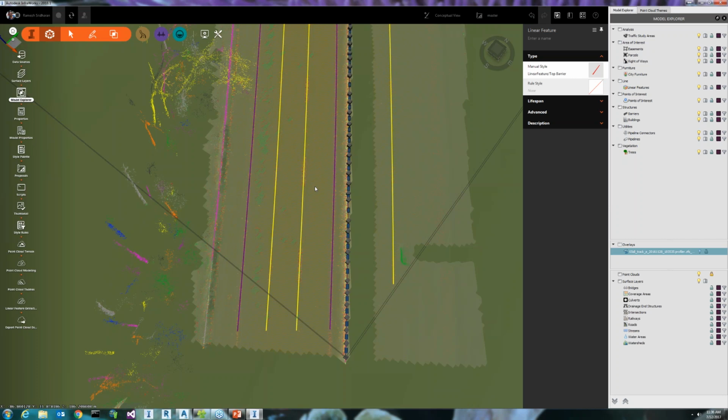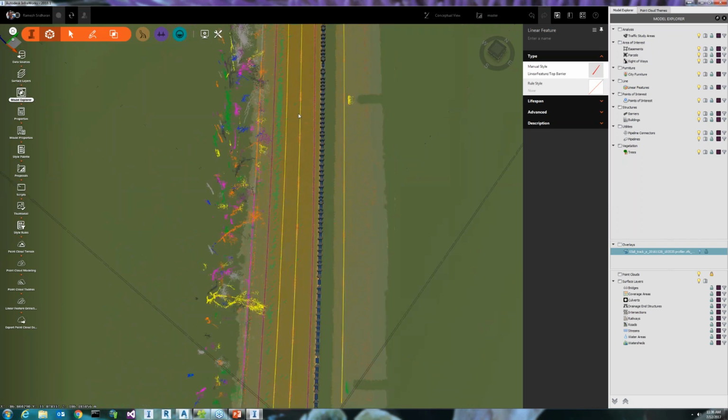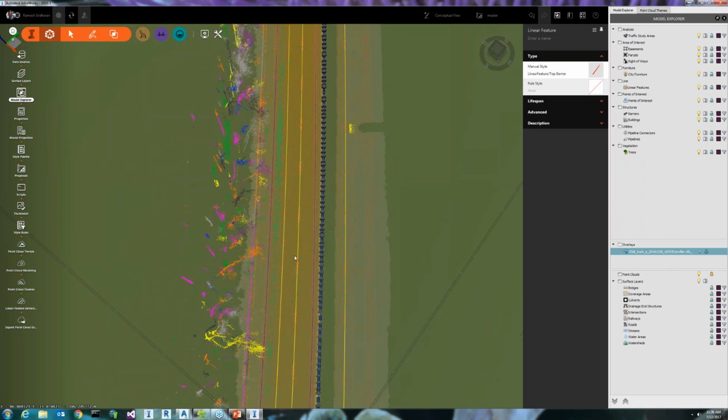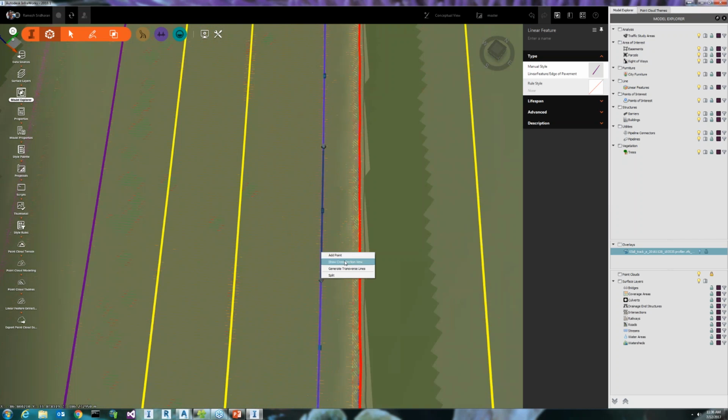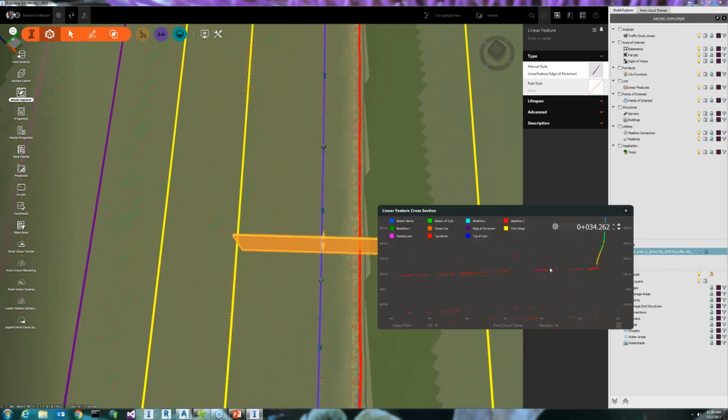Okay, great. Thank you. Perfect. So now the top of the barrier has actually been extracted. I'm going to pull it, just starting somewhere random here. Now go to the cross-section view, and right there you can see I just picked a random area, and that's the top of the barrier it actually picked. Maybe if I had picked manually, I would have made a really slight change, but the software did a really good job doing that by itself. So now, how do you extract things manually?